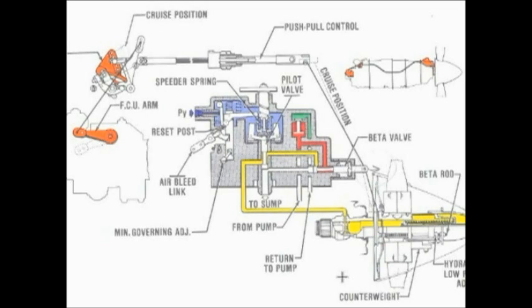Low blade angles and reverse angles are scheduled by the cam box and cable arrangement that is connected to the propeller lever. Movement of the power lever into the beta range moves the cam cluster and levers such that the complete integration of the propeller blade angles and power application is achieved. There has to be perfect rigging between the throttle quadrant and the front of the engine.